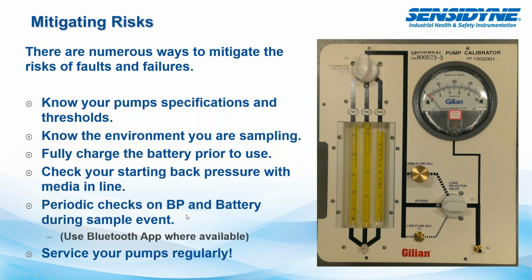Periodic checks on the back pressure and battery during a sampling event. I would say back in the day when I was a consultant, we didn't have fancy electronic pumps. We actually had to go out there and fiddle with the pumps several times during the day to make sure that the pump was running good, that there were no faults occurring, and that, if there was a battery bar in the pump, that it wasn't drained. But in a lot of cases, it was whether the pump was shut off when I walked up to it or not. With today's modern pumps,